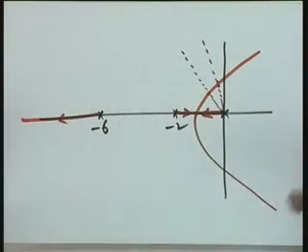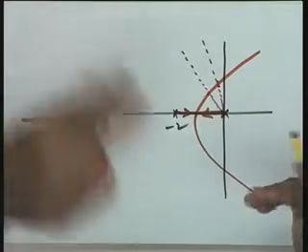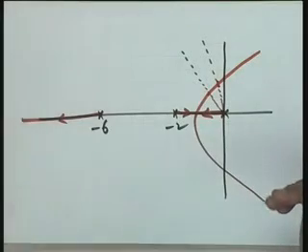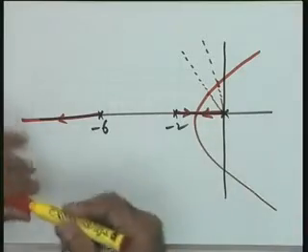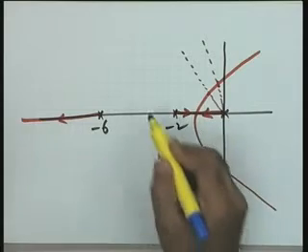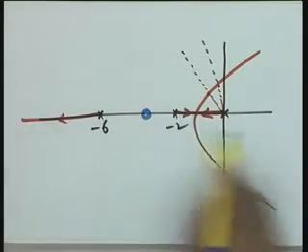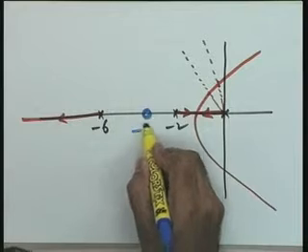So, what you really want? You want the transient accuracy to be preserved without losing the steady state accuracy or vice versa. So, what I suggest is this, that without giving you the reason as to why do I suggest, let me say that to this particular plant I introduce a 0 at this particular point between the two poles, let us say at -3.